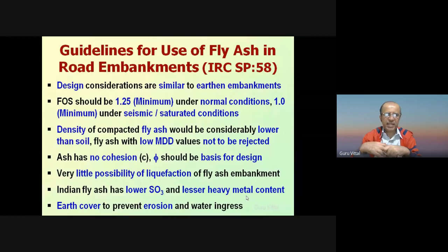Ash has no cohesion. The C value is 0, and the phi value should be the basis of the design. Whatever phi value we obtain using a direct shear test or a triaxial shear test can be used for our design purposes. Very little possibility of liquefaction of fly ash. So this is another important point.